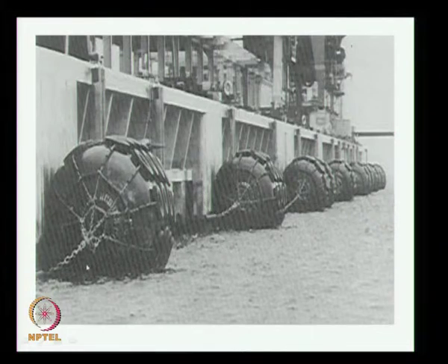This concrete face should be from the lowest water level to the top of the berth, unlike a cell fender where we need this portion of the structure only from mean sea level to top level of the berth. If you want to fix a floating fender, you need it from the lowest water level to the top level, that is the advantage. This is the diameter and this is the length of the fender.